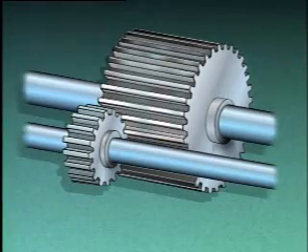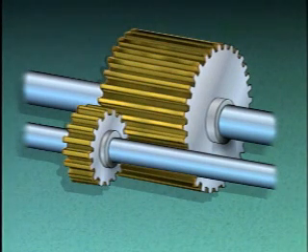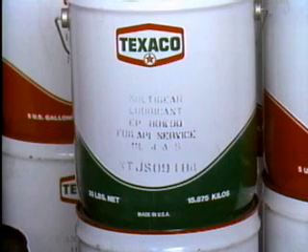As gears mesh together, the teeth rub against each other under great pressure. This severe rubbing can actually wipe away the protective lubricant and expose the bare metal. Gear oils usually contain chemicals called EP additives to protect metal surfaces against wear from rubbing. EP additives are used in greases or oils to form a protective coating on the exposed metal. The coating stays in place and prevents metal-to-metal contact, even if the lubricant is rubbed away. Lubricant containers usually have EP on the label if they contain an extreme pressure additive.